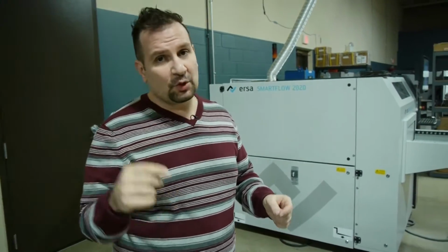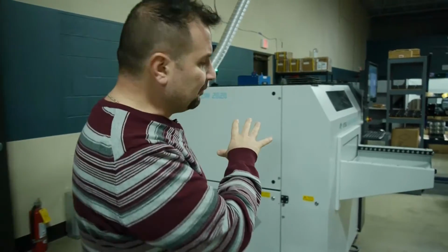Now, through-hole components are basically through-hole. They go through a hole on the circuit. Surface mount components are the components that sit on the surface. So there's paste, the component sits on top, it goes through the oven, gets reflowed. That doesn't work for through-hole components. Now, they have a separate machine for that.